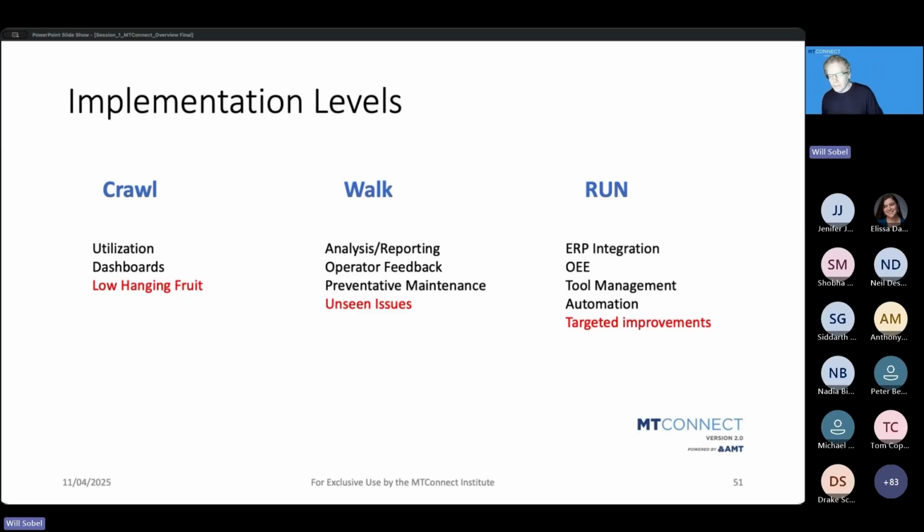And then you can get into things like preventative maintenance. This is not as hard as it seems. Your first step is maintenance on fail. Second step, scheduled maintenance. I'm going to schedule maintenance every, let's say, 6 months for doing X, Y, and Z, which may or may not be needed. Let's say the machine hasn't been used for 6 months, or it's been used half the time for 6 months. Why do that maintenance? Could it actually cause more problems than it's worth?